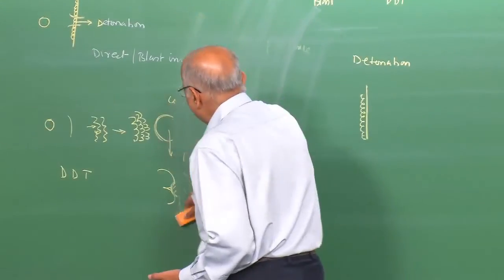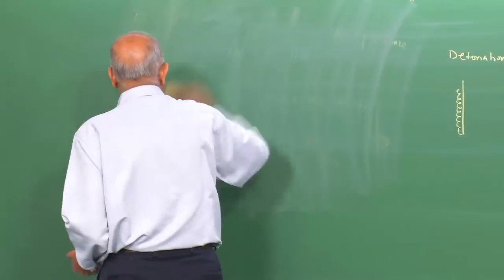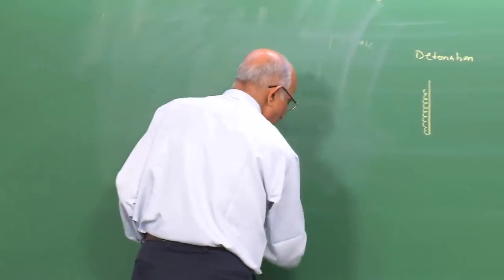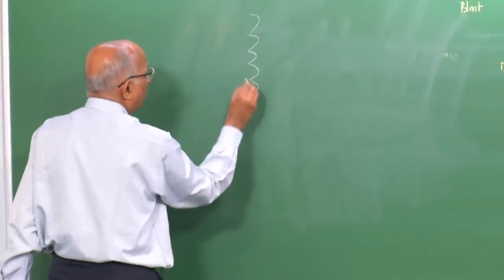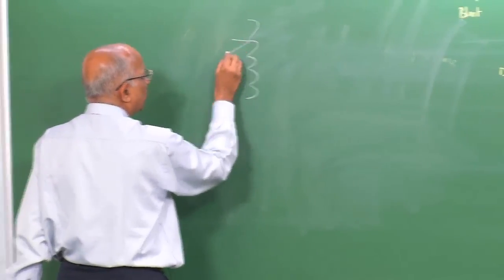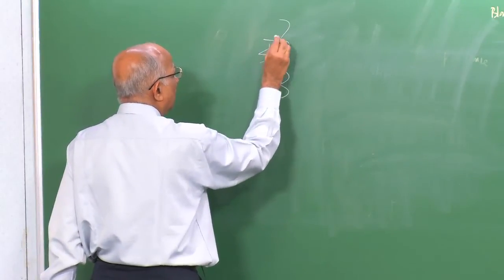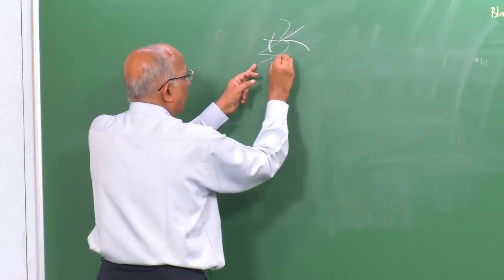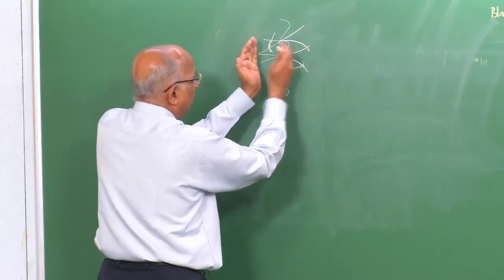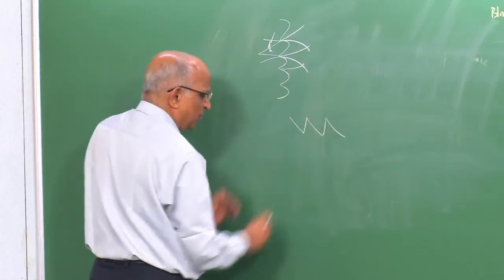We like to work with a simple model of a detonation, namely a one dimensional model. But we said, well, a detonation is not one dimensional. The front consists of corrugations like this. I have transverse waves which are moving, maybe one here, maybe one here, and it intersects, and therefore I form another cell of a detonation. Within this, the velocity keeps changing, velocity picks up and changes.